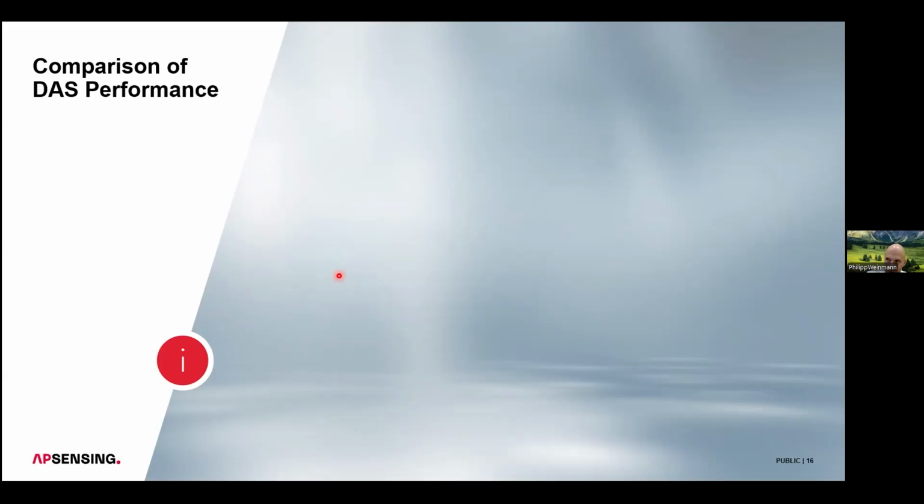All right. But there would be a point where, if we press too much, your phase differences would exceed 2 pi. So basically what you are referring to is the dynamic range. Yes. If you exceed the dynamic range, then you cannot track back the deformation, and the dynamic range depends on your measurement configuration. The higher the pulse rate is, the larger your dynamic range is. That's why, for this setup, I used a high pulse rate so that my dynamic range is larger.